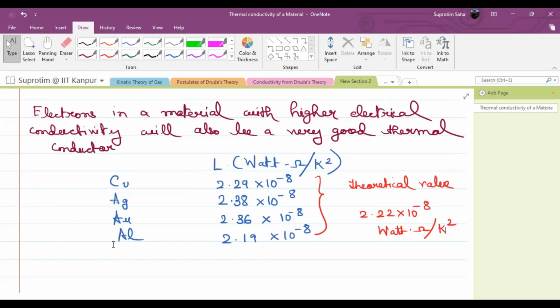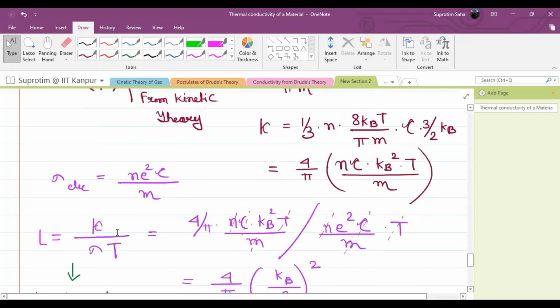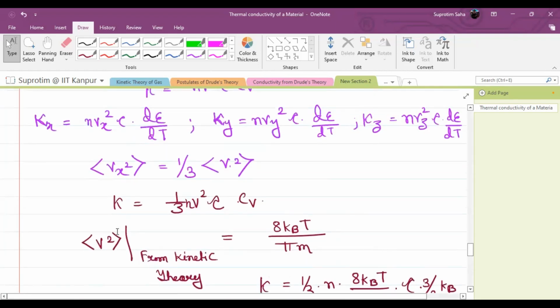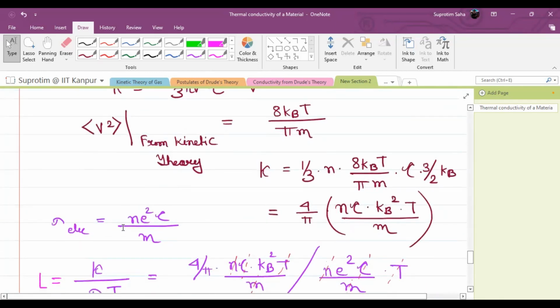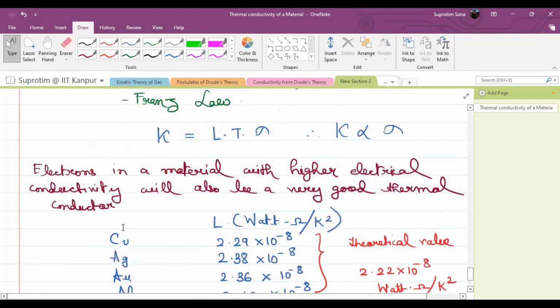We derived that for thermal conduction to happen, you need a temperature difference, and not only that, a temperature gradient across the sample, meaning the temperature difference over the distance it's carried through. We wrote down a formula for the thermal conductivity, 1/3 n times mean velocity times tau times the specific heat. It also has some alternative forms which we wrote. So we just stop here.